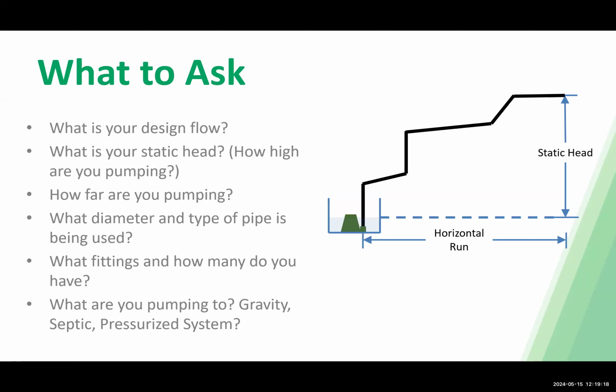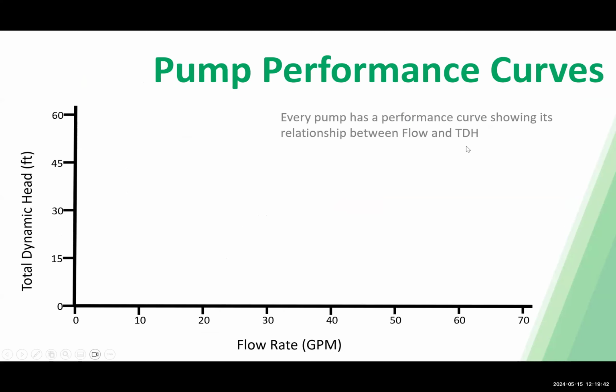So everything on this slide, other than your design flow, is going to be used to determine the pressure, or your total dynamic head, that your pump needs to be capable of pumping against. And we're going to go a little bit deeper into that in the next few slides. So first off, though, let's cover the pump performance curve.